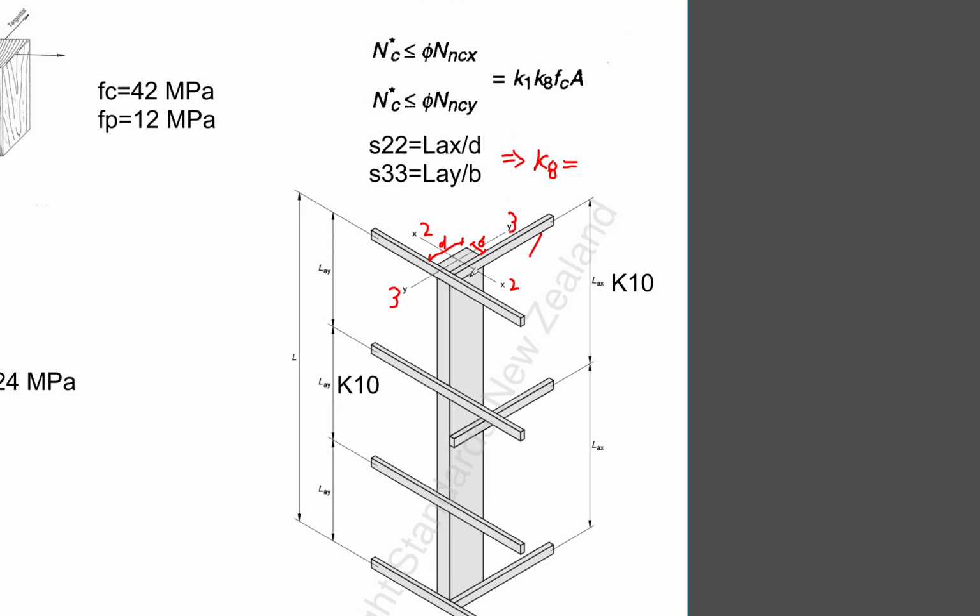In terms of the major axis, the X direction, what is restraining my column buckling is these outriggers protruding from the column, spanning between these two. That would be my restraint to the major axis. If my beam is going to buckle, it's going to be that shape. That would be the major axis buckling.